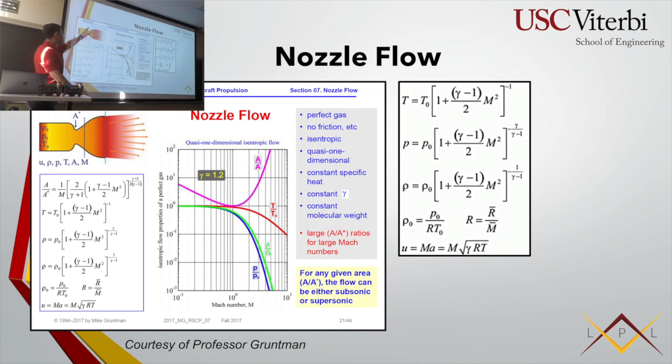So that's why it's always critical to get the throat correct. The end here doesn't really matter too much, because you want P equals PA, but we also just mentioned when your rocket's launching, your pressure outside is changing 24/7, like literally every second it's a different pressure. So it's impossible to have P equals PA. So you kind of find where something happens, and that's where you have overexpanded and underexpanded.